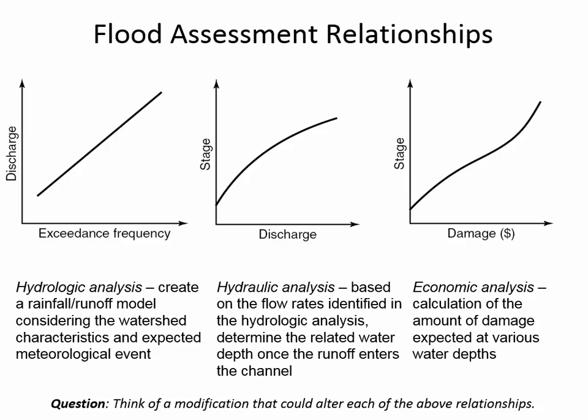Okay, less urbanization, or when urbanization has occurred, okay, put the water somewhere else, like in a pond. And so if you put in a retention pond, remember all the things we're trying to do is we're trying to slow down the water and increase infiltration. So maybe we could disconnect people's roof drains and try and put in little rain gardens next to their house with amended soil and try and get the water seeping down into the soil.